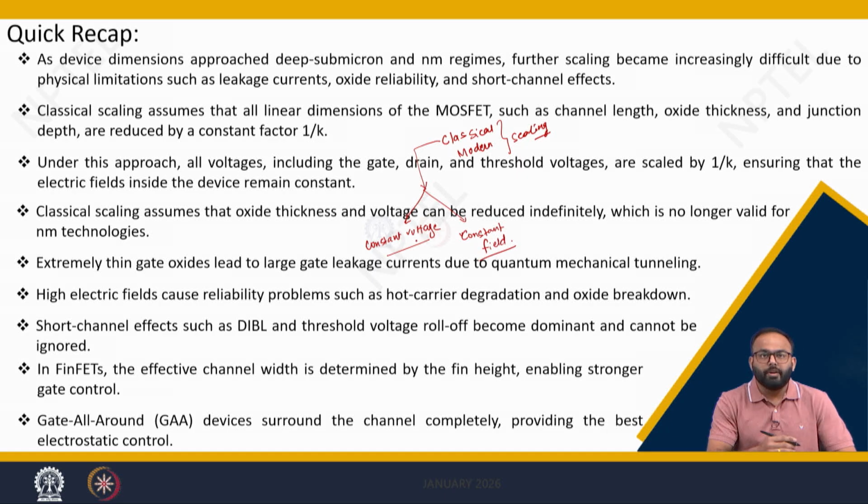However, when we are approaching the new emerging devices, these set of rules will not fit everywhere, and hence we need to use some scaling parameters case by case. That is what we called quasi-constant scaling, meaning we will decide a scaling parameter k dash, which is not exactly k or not exactly 1.